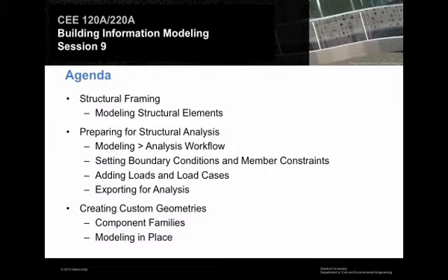And I'm going to show you how you create a very basic structural skeleton and take that forward into doing analysis. The idea is that you can not only put placeholders in there for what the structural element sizes may eventually be, you can take those elements right out of the BIM model and ultimately take those over to a structural analysis package. Calculate what the loads are going to be, or what the stresses and strains on the beams are going to be, and size them appropriately.